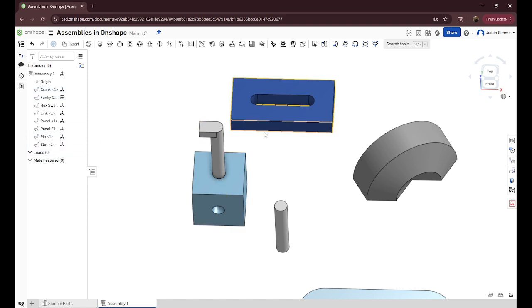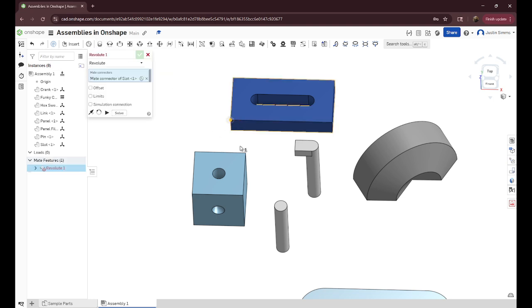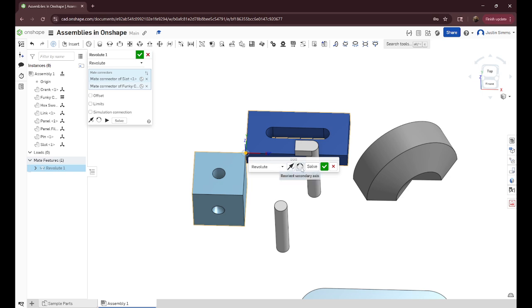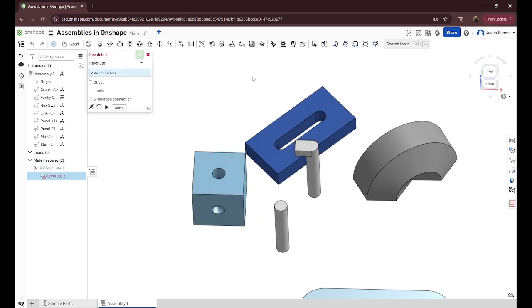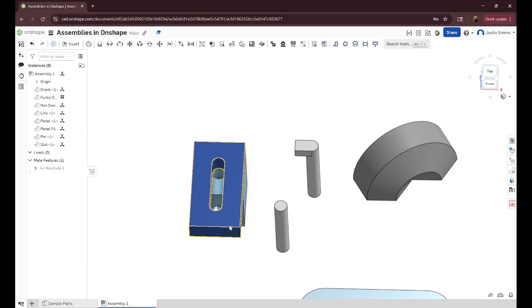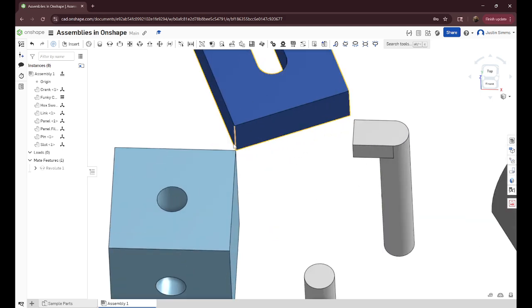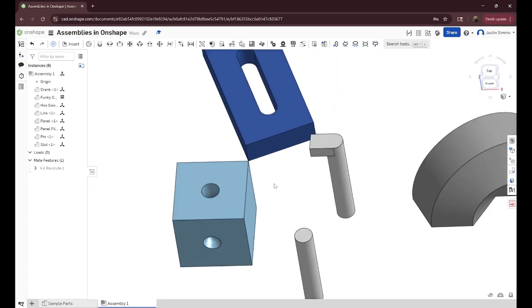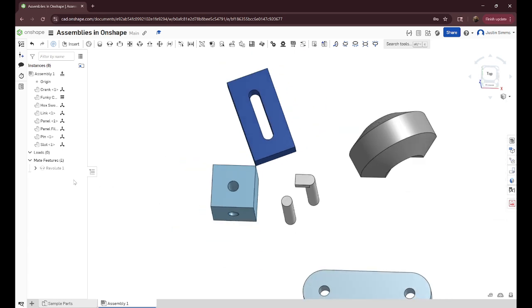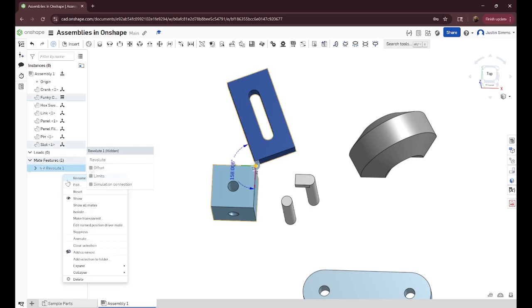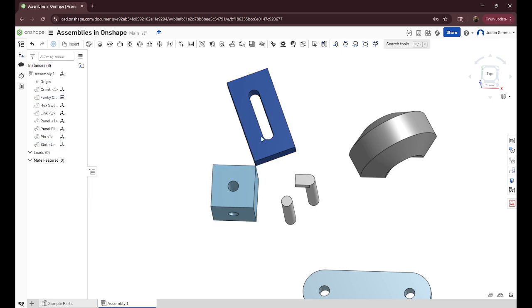And then you can also do these with non-cylindrical parts. So for instance, I can do a revolute mate between this corner and this corner. And then we'll flip this over. So it's like this, and now this part can spin around there. This physically wouldn't really make sense, but if you're doing a test part or something and you wanted to have it locked like this, you could. Or if you wanted to simulate a coding feature that hard stops it there. Well, stops because it's code.